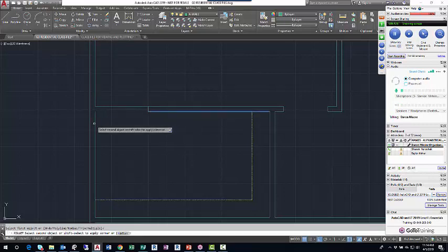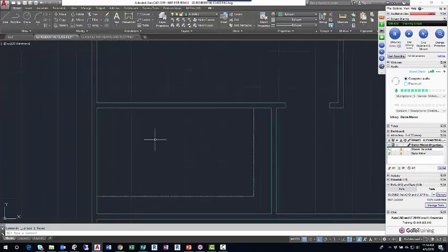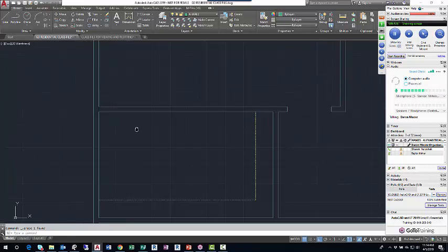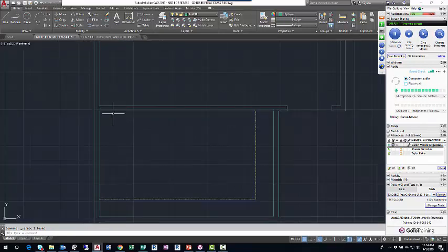So I've got most of my wall lines where my horizontal walls meet the vertical wall. They're all trimmed out. So it'll be an offset and extend and trim, but all the doors are set 6 inches off of the nearest wall at the hinge side. So if I click offset, I'll type the number 6 and press enter. Left click my wall line, move right and left click in bedroom 3.